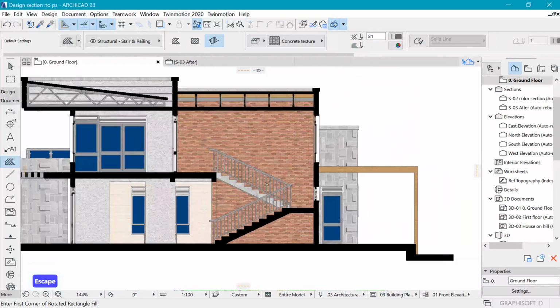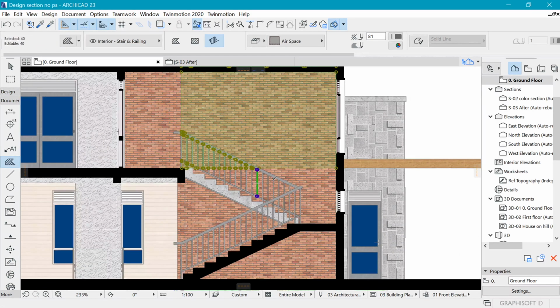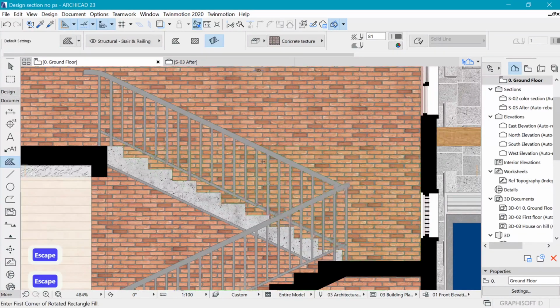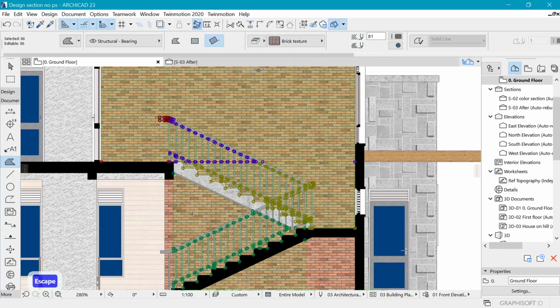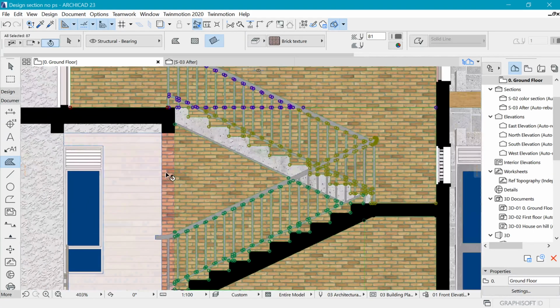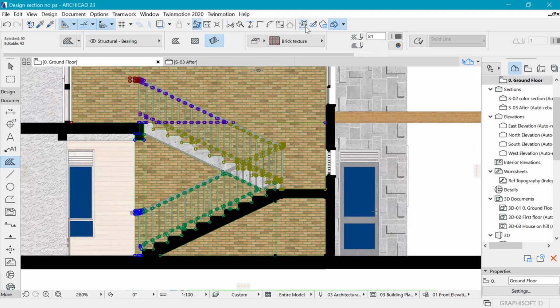So I'll go ahead and do the same thing to this brick, and you realize it's really pretty hard to select everything which is in here. Actually it is grouped already, which makes it easy to select, which is really good. So once I have them selected, because the grouping is unchecked, I will Control D to drag, and then Control again to have that plus to make a copy. Then I click once and click twice to place the duplicate in the same place.